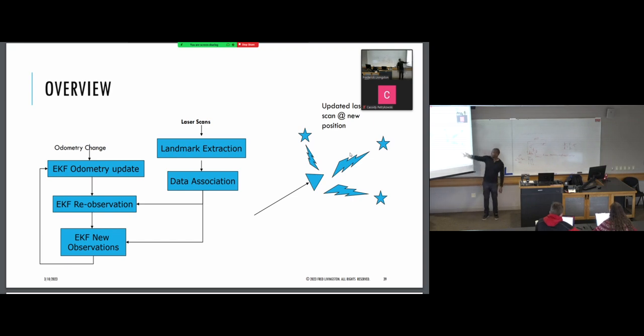It sees the three objects again, and it computes its position again. So I have two different pieces of position information: one I computed from my LiDAR, and one I computed from my odometry information. And they may not match. I may have a really high quality LiDAR system and a low quality IMU, or I may have a high quality IMU and a low quality LiDAR.